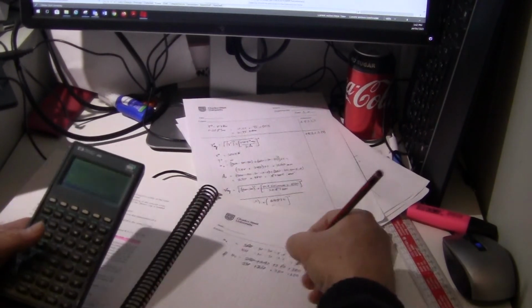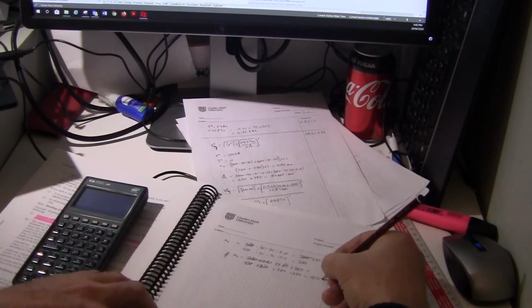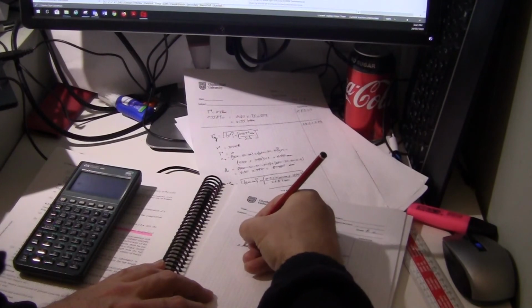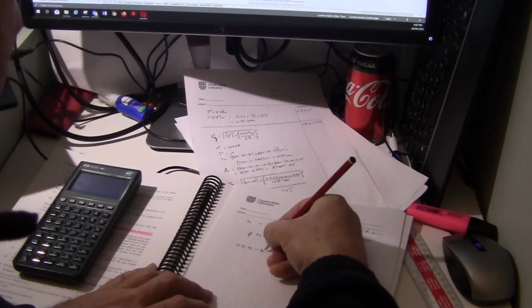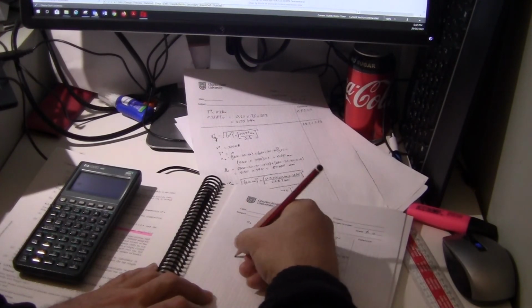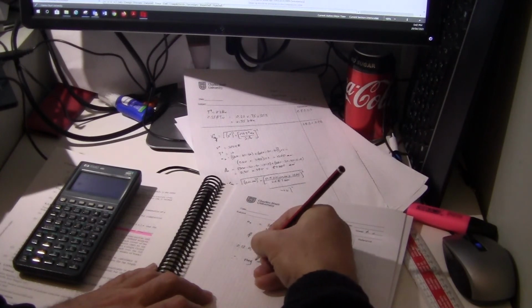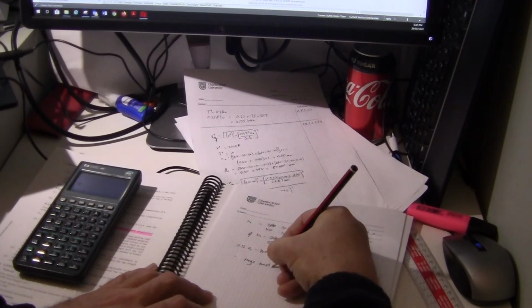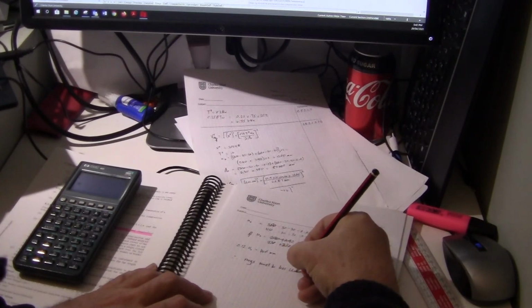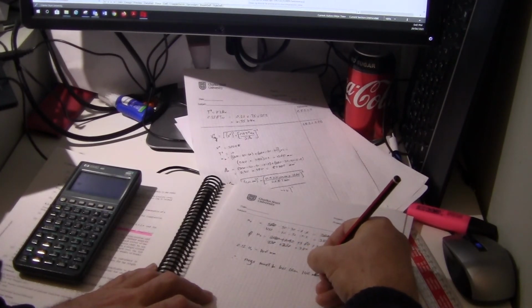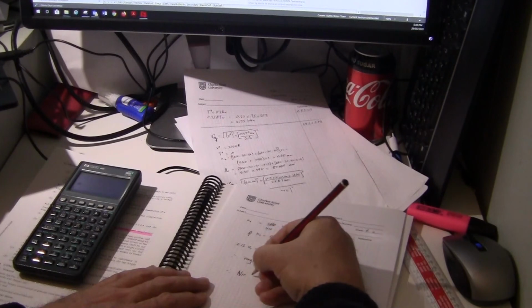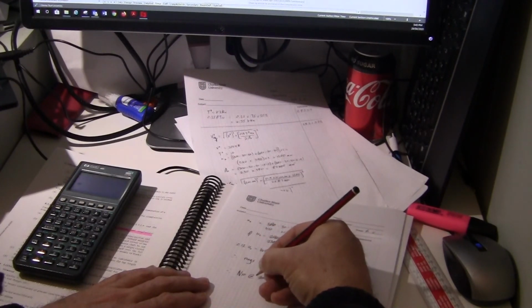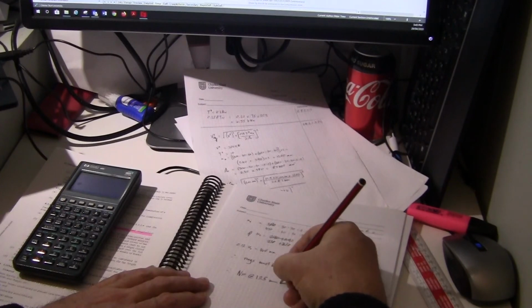So add all that up, I get a perimeter of 1220 millimeters, and I go 0.12 that, so 0.12 UT equals 146 millimeters. So therefore, rings must be less than 146 millimeters apart, and you generally go to the nearest 25 millimeters, so therefore N10 rings at 125 millimeters center to center.